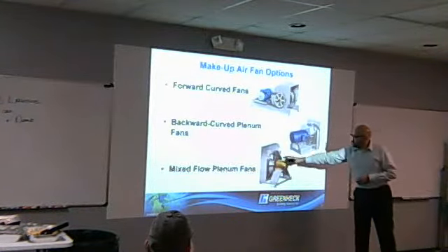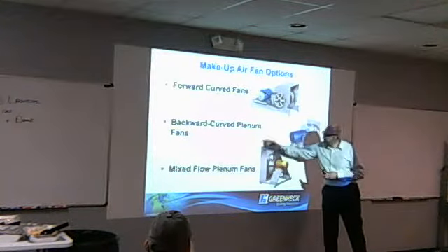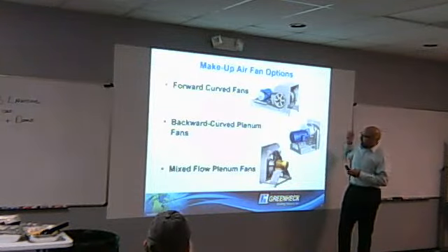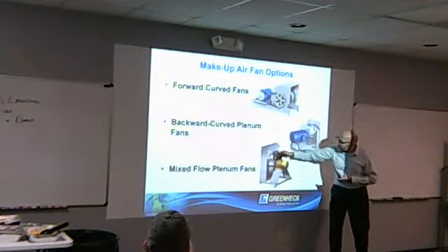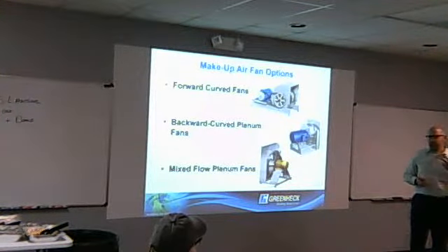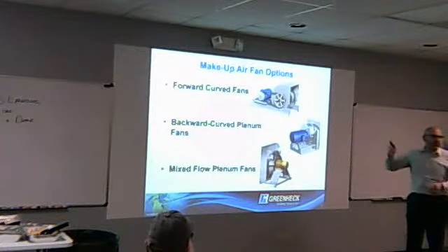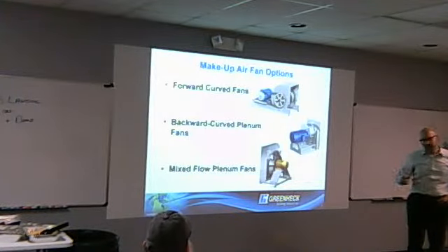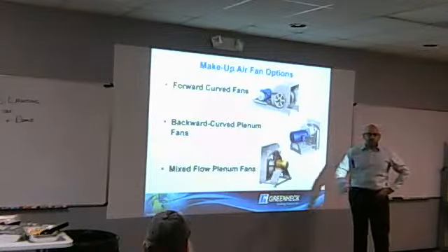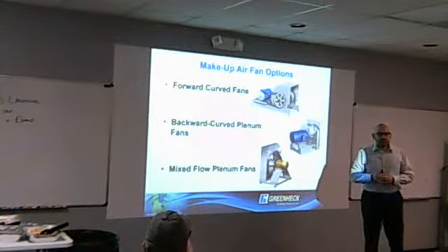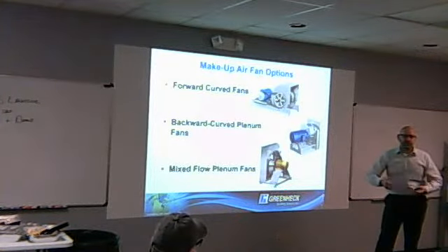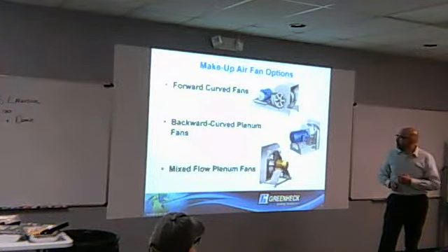And the last one, mixed flow plenum fan. So plenum, but the difference here is the mixed flow, instead of the air coming in and coming out at 90 degrees, it's coming out at 45 degrees. And it has a different sound profile, but it's more efficient. And I have a graph that will show you the efficiency gains just by using a mixed flow plenum. And then direct drive arrangement. More and more we see direct drive arrangements simply because we eliminate the maintenance of the belts, misalignment, the loss of efficiency, things of that nature.